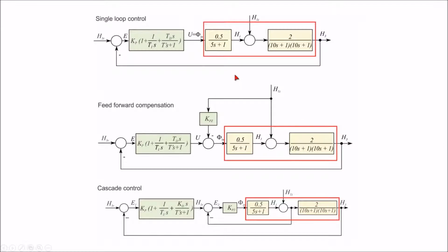This presentation will demonstrate how to develop the simulation scheme for the hydraulic plant. It consists of two parts. The first part is the transfer function GP2, and the second part is the transfer function GP1. The input is the control variable. This is actually the flow into the first tank, and the output is the level in the third tank. There is also the disturbance, which accesses the process in this midpoint.